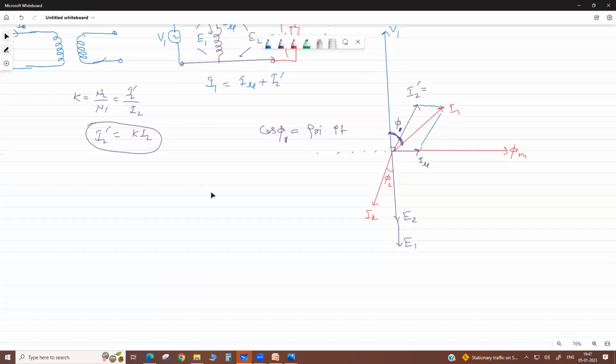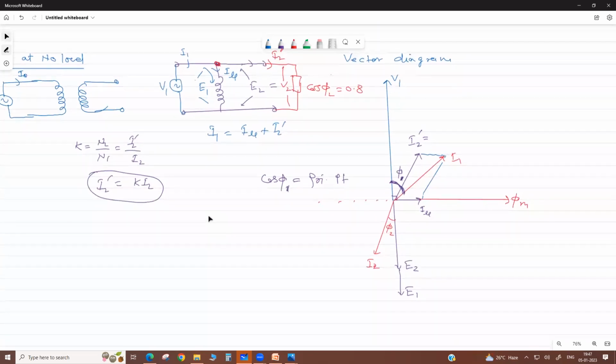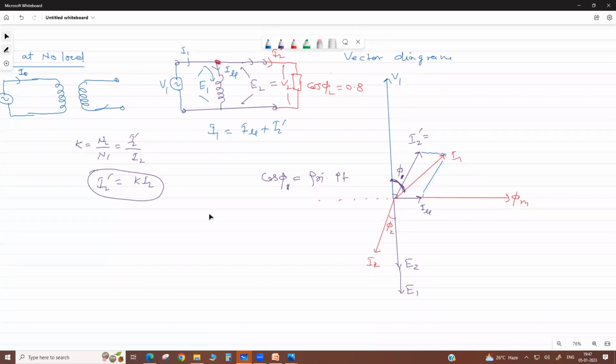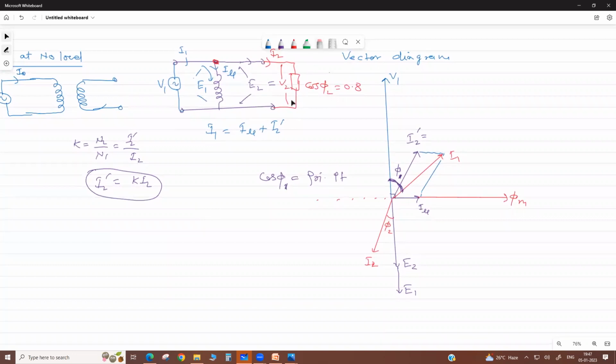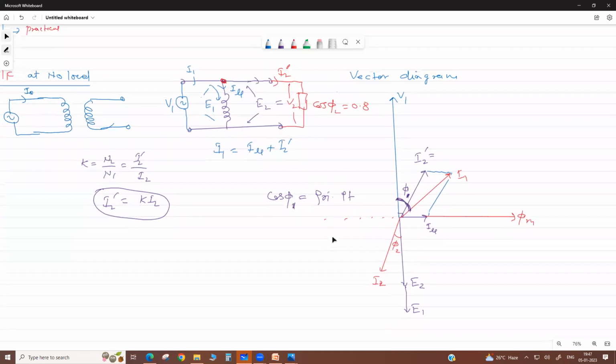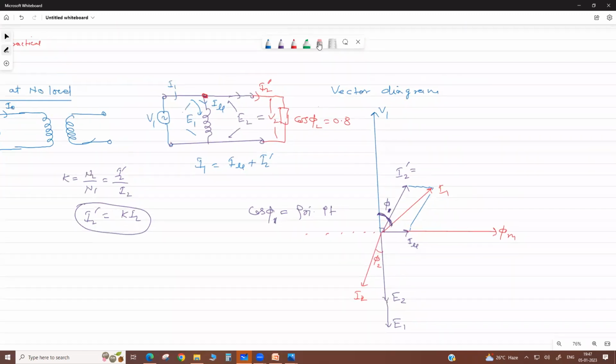Okay, dear. Actually, today I think you got bored because it is totally concept-wise. But in the next class, we discuss a numerical on this, and it is very important. Recently, they also asked one question on this. Now, we do not take it as 100% ideal. We only neglect the primary and secondary impedance. The magnetizing branch we consider completely. Then we draw the equivalent circuit.